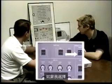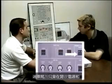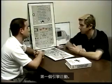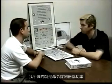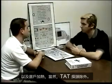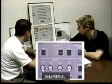What if I was to select the switch to on? Selecting the on only really does something between power on and the first engine start, and all I'm doing is commanding low power to the probes and window heat, with the exception, of course, of the TAT probe.